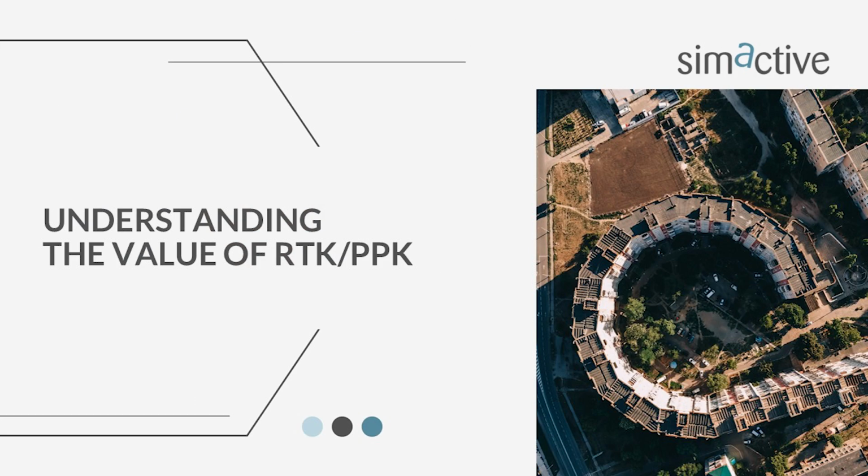RTK and PPK. I feel like these are two terms that get thrown around a lot in our industry, sometimes without clarity. So in modern photogrammetry, precise positioning is often the foundation of accuracy, right? And high quality GNSS and IMU data helps reduce reliance on dense ground control points. It helps improve the AT consistency, aerial triangulation, and it helps speed up production. So David, from your experience, perhaps we can start actually with what is RTK and PPK. Can you explain that to us in simple terms?